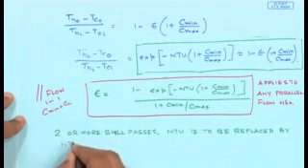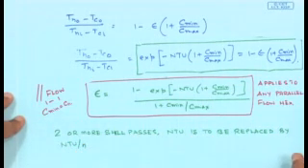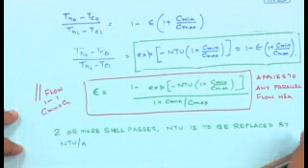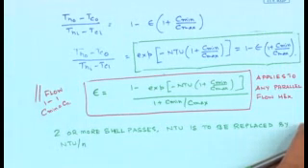by NTU by N. Now, for a boiler or condenser, let's say the temperature of one of the phases will remain constant. So if it's a case of steam condensing on the outside, then the temperature of the hot stream is not going to change. It will remain constant at that value. On the other hand, if you have evaporation taking place, then the temperature of that phase will also remain constant. So there's not going to be any temperature change for the case of boilers and condensers. So let's see what expression epsilon would take for the case of boilers and condensers.